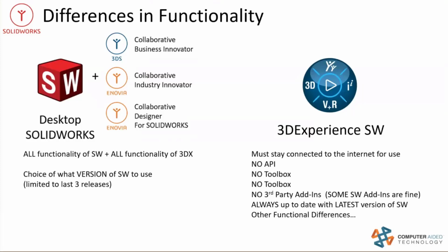I like toolbox. Okay. The other thing is no API support for third-party applications. So if you're currently using tools like DriveWorks or Power Surfacing or something that's a SOLIDWORKS add-in, that is not supported for the 3D Experience SOLIDWORKS, because when you go to save files, you're actually saving to the platform. You're not saving those files locally. So that is a big thing there.